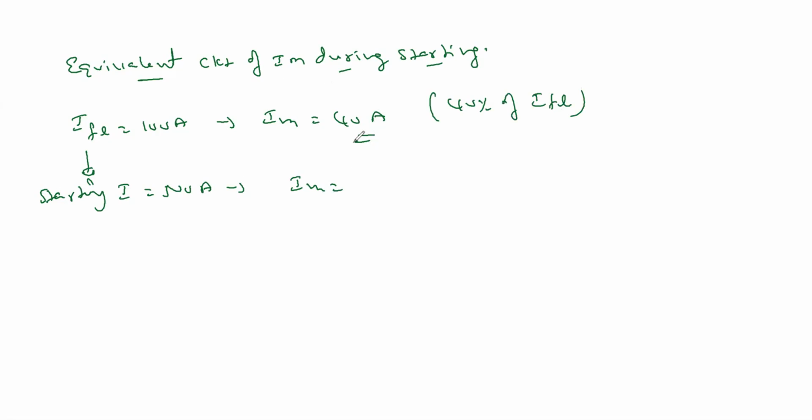तो कोर को मैग्नेटाइज करने के लिए 40 एम्प्स है. जब आप 500 एम्प्स को भेज रहे मशीन के अंदर, उस समय भी इसको 40 एम्प्स ही चाहिए. ऐसा नहीं कि मेरे पास 500 एम्प्स है, इसमें तो 40% लेंगे, ऐसा नहीं है. अगर मान लो आपने 100 एम्प्स भेज दो, 60 भेज दो, 30 भेज दो, 50 भेज दो, जितना भी करंट आने दो अंदर, तो मुझे चाहिए 40 एम्प्स कोर को मैग्नेटाइज करने के लिए. ठीक है, तो अभी 500 एम्प आ गया ड्यूरिंग स्टार्टिंग में, तो अभी 40 एम्प्स ही चाहिए.